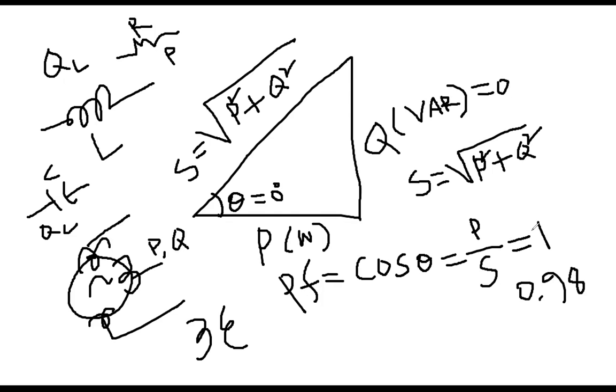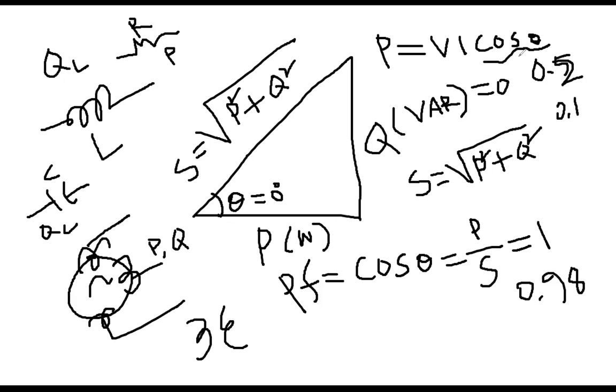And then, everybody, what is the significance of this one? You see, because P equals this real power, VI cosine of theta for a single phase system. In case of a 3-phase system, it will be multiplied by √3. So everybody see, you are calculating P = VI cos theta. So whatever your voltage and current is, it is dependent on power factor. Now, for example, if you get 0.5 here, then your power value is getting halved. If it is 0.2, again reduced. If it is 0.1, again 10 times decrease.